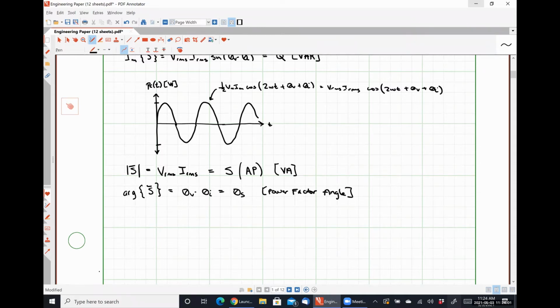This is a complete aside, and this was covered in engineering 121 as well as 221, hopefully. But the resistance of anything really can be determined as a function of its geometry as well as its material. The resistance of something is rho L divided by A, where rho is its resistivity, L is its length, and A is its cross-sectional area. Because of the inverse relationship between resistivity and conductivity, this is L over sigma A, where sigma is conductivity. You won't ever need to know that for this class, but it's just a general thing you probably should have heard of by now. That's a terrible looking sigma, but I can't draw it any better.